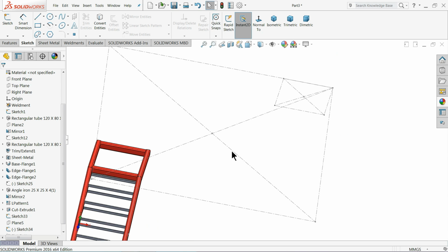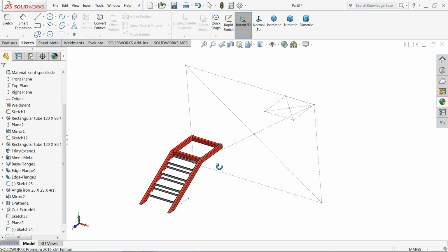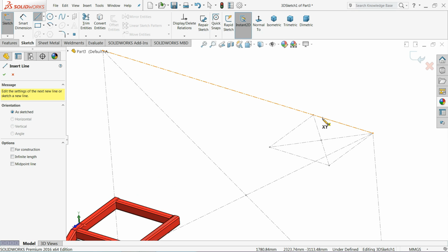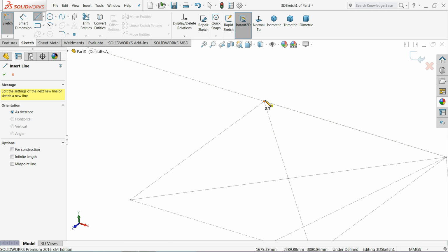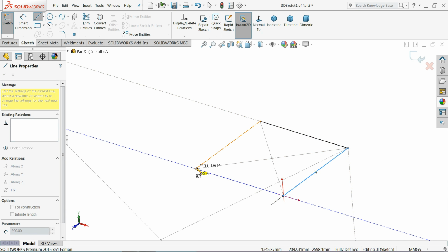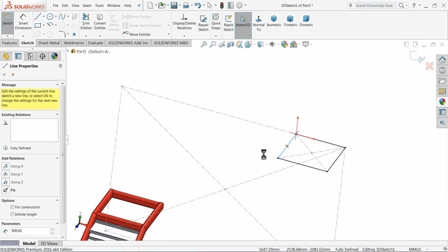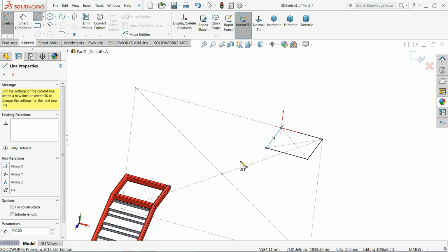Now we want to draw one more ladder here, so first we need to connect this one. So let's choose here 3D sketch, select here line. First we will convert this one up to this face, this face, this face and this face. Now it is already a ladder predefined path, so it's not much difficult for us.